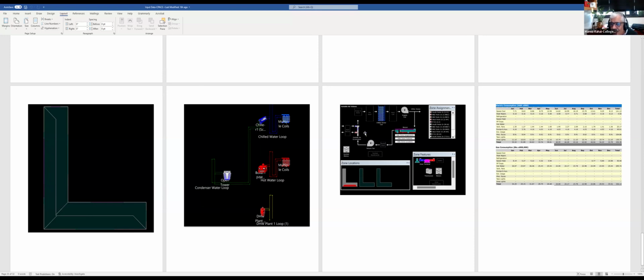For our case, the majority comes from electricity and also gas consumption to heat the water, based on the hot water system that we have. It gives you how much electricity you will use on a monthly basis, and then it gives you the total. And again, once you have the total, as I said, you can convert them to kBTU and divide them by square footage.